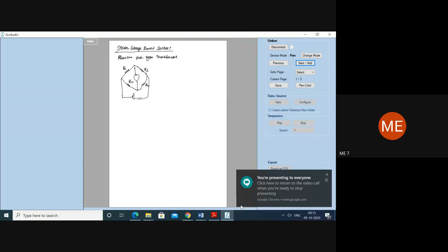Let's say in the case of a load cell, or a simple load cell experiment we have done, you place the strain gauges at the 4 different corners. Or the other possibility is, maybe I want to measure the force here. I have kept a cantilever beam with 4 different strain gauges over here.